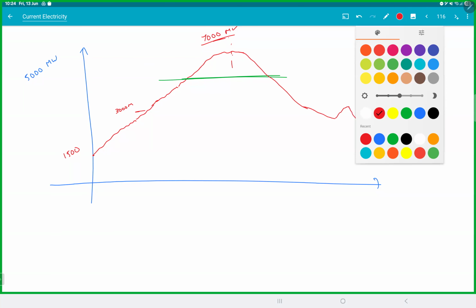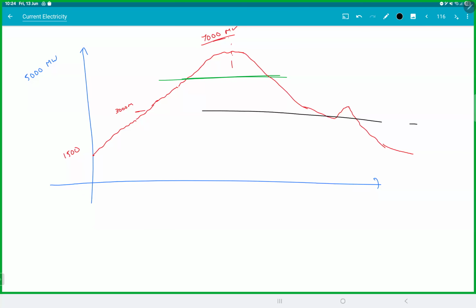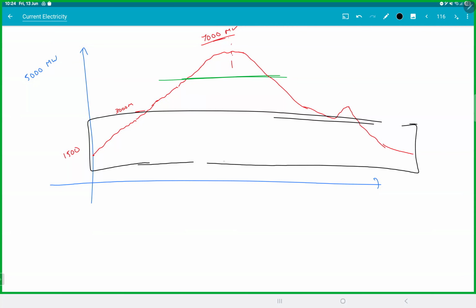Now, the problem I'm facing here is that during night time, our generators are just sitting idle without doing anything. So during night time, somehow I could generate electricity, store it, and use it in the daytime. That would have solved our problems. Now, storage is a problem. Every time I try to store 100 watts, I can only store 50 watts. And when I try to recover, I lose 50% again, so I get 25 watts. You're getting the problem? Storing, I lose half. Recovering, I lose half, in the most efficient batteries. In real life, you won't even get 10% out. Too much wastage, not efficient.